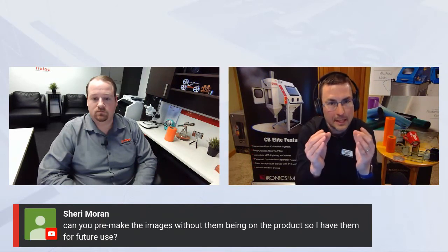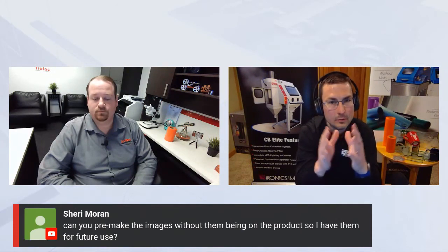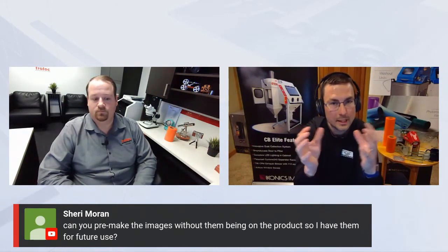No, but what I could add there, because back to the question earlier about the green versus the orange laser mask material: the green film, when you laser etched it and left the piece out for a long period of time, eventually that green mask may shrink a little bit and you distort your image. The laser orange was made to hold up. So you can laser abrade all your images and use them months later or whenever you need to. The orange film is not going to shrink or distort over time. So you're able to do pre-made images on glass.